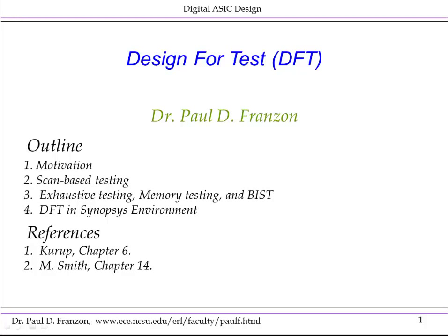The topics we're going to cover are as follows. I'm going to describe why we do this and illustrate how it is done. Then we'll talk about the dominant design for test technique, that is inserting scan chains to access internal nodes so we can test that they're actually okay. I'll discuss some other techniques, including functional test, memory test, and BIST, built-in self-test, and finally talk a little bit about how test insertion is done within the Synopsys environment, and some reference areas given at the bottom.